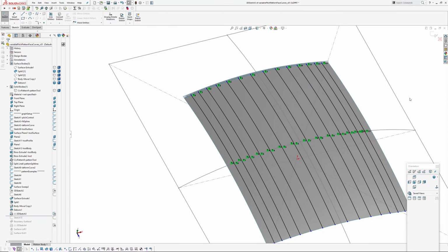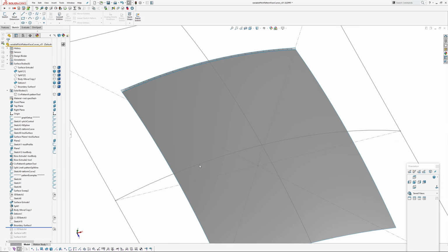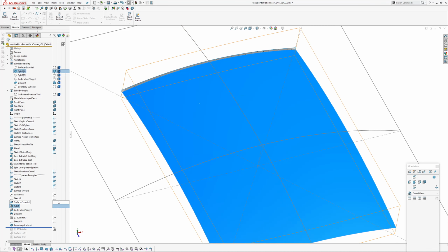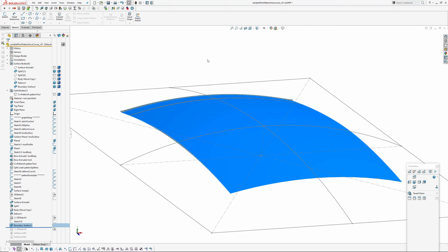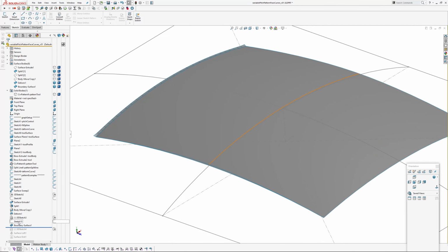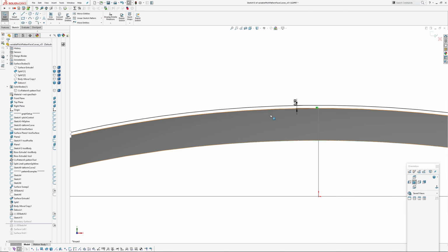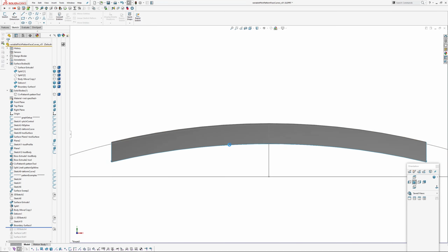So I've done that with every second curve on that face. I'll go OK, and now I've created a second surface, the trough surface. I'm going to create a surface that's above the main swept surface, which is like the peaks of the ripple. I've done that by making a sketch. I've offset the centre of my swept trim surface there, 0.5 up.